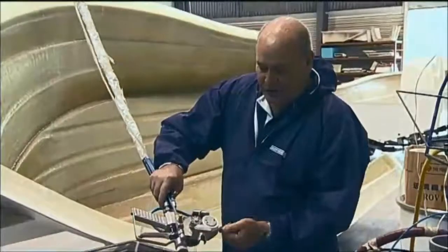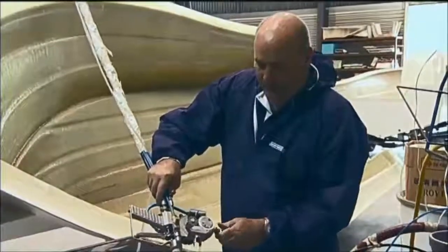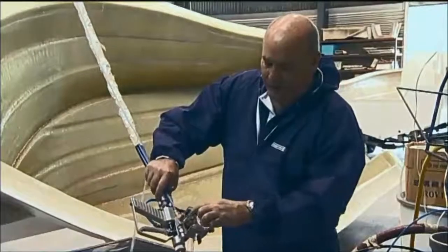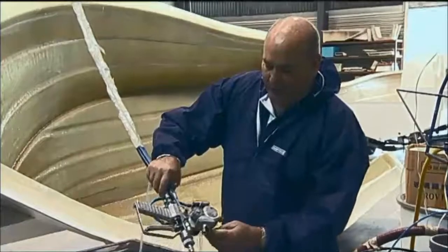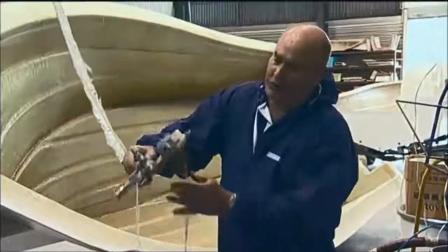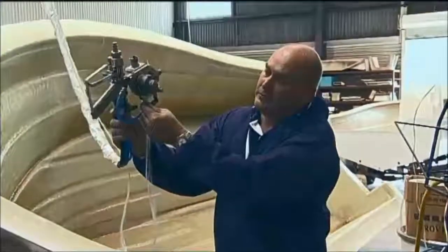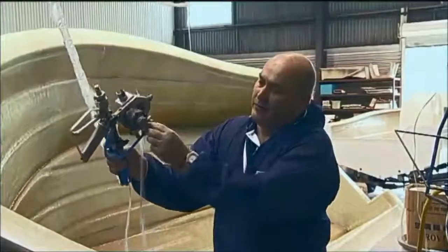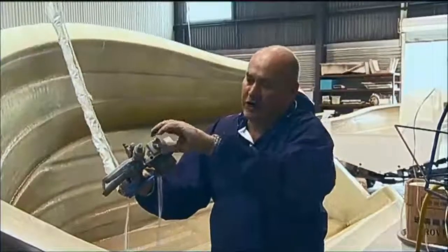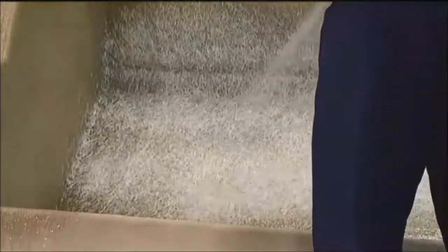We can adjust the tension of the rubber. We can have any amount of blades that we require, the strand length. And we can make adjustments for motor speed. So we can adjust the speed of the motor, and with this adjustment here, we can introduce air and fan out the glass, and we get the right adjustment to go into the fan of resin.